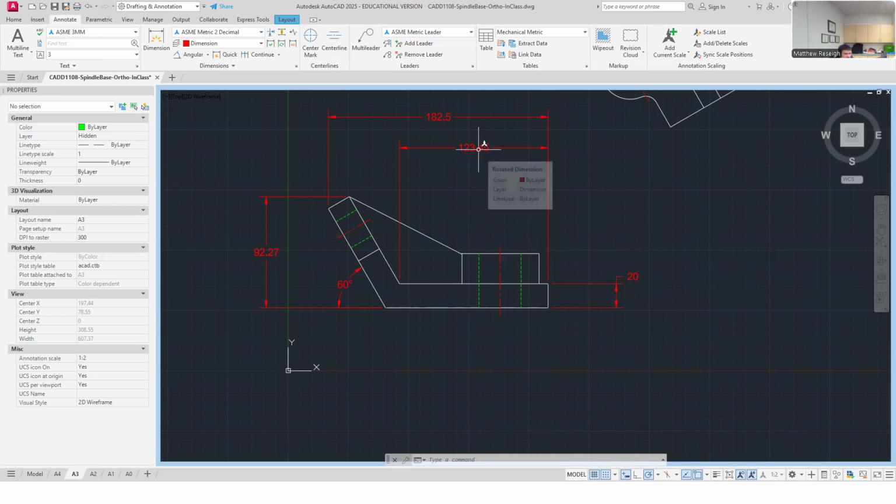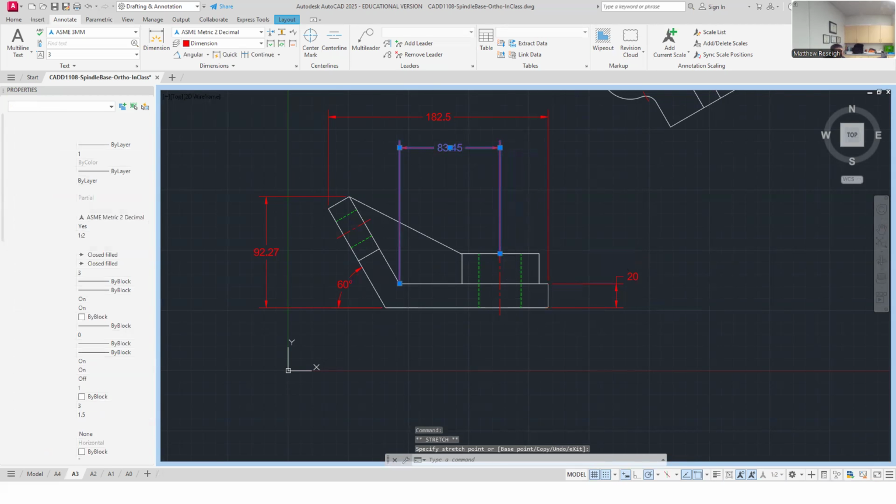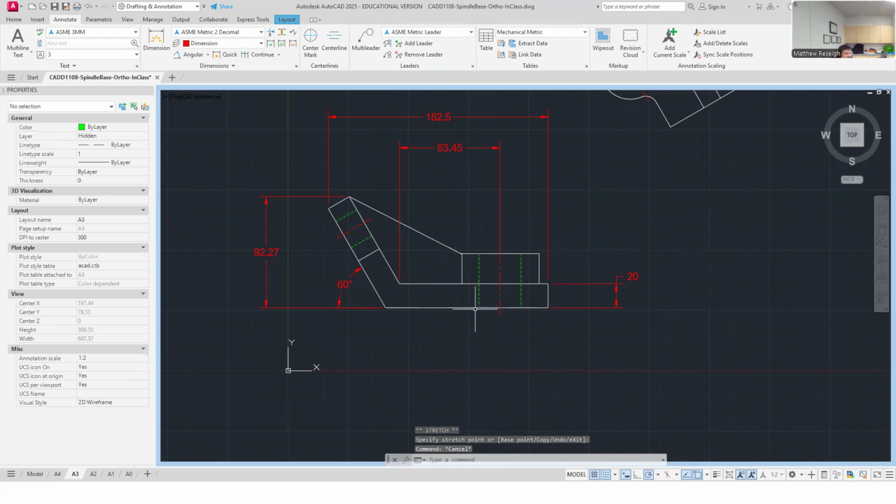maybe I'm going to change this a little bit. I'm going to say maybe this one is actually better pulled from right here, because this is a better control than that outside radius edge. So now if I'm thinking of this part here, I don't want to start controlling stuff from the right side. I'm going to start controlling stuff from here. And so I'm going to say this plate now is from here to here. And now that really helps me with this plate as well, that this point is established from that control,